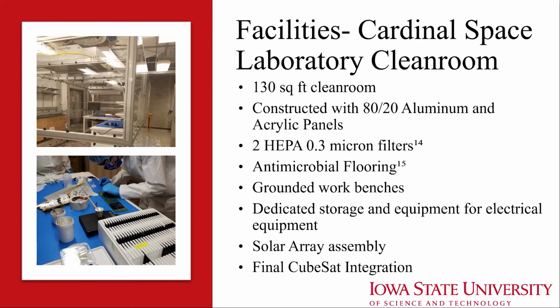The Cardinal Space Laboratory Cleanroom, shown in the upper image, is a 130 square foot cleanroom that provides a large work area for integration and assembly of sensitive components. The frame of the cleanroom was constructed out of 80/20 aluminum along with acrylic panels, with easily cleaned antimicrobial flooring. It maintains its air quality through two HEPA 0.3 micron fan filter units.